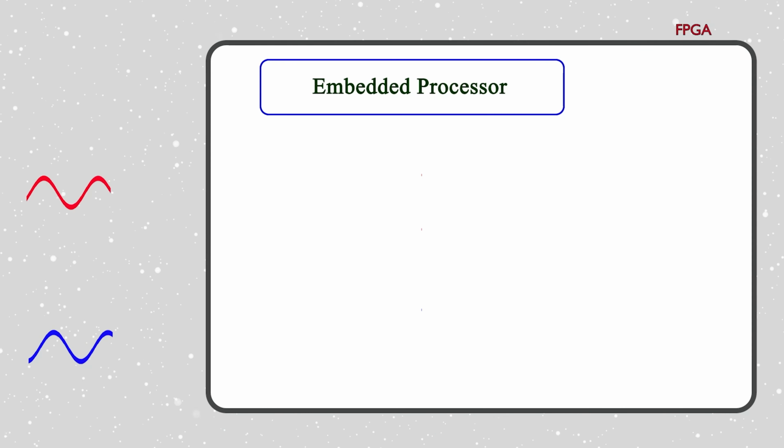Now we've also written some interface code for the FFT. So we've got a pair of FFTs, one for the voltage and one for the current. And in the next video, the first thing we'll do is analyze the output from the FFT just to see that the input signal is actually being split up into the frequency domain and the harmonics.